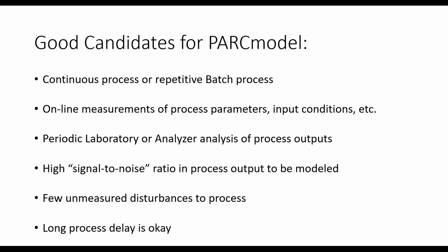And so in a PLS model, essentially you're taking a list, virtually unlimited number of input variables, and using data from the process to crunch through a bunch of math and determine how all those input variables affect a single output variable. And what you end up with is a big linear equation with steady state gains for each input variable as they relate to the output variable, and of course a y-intercept.